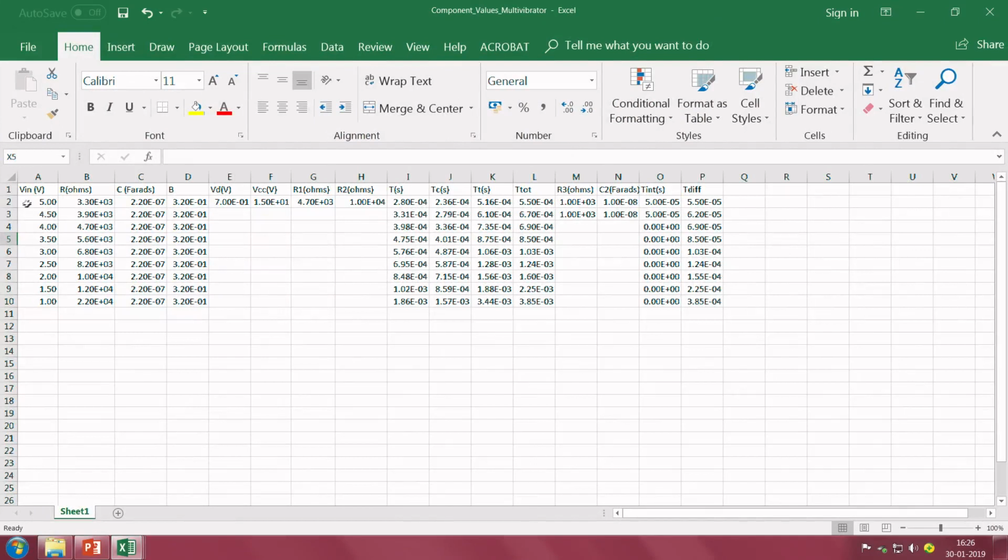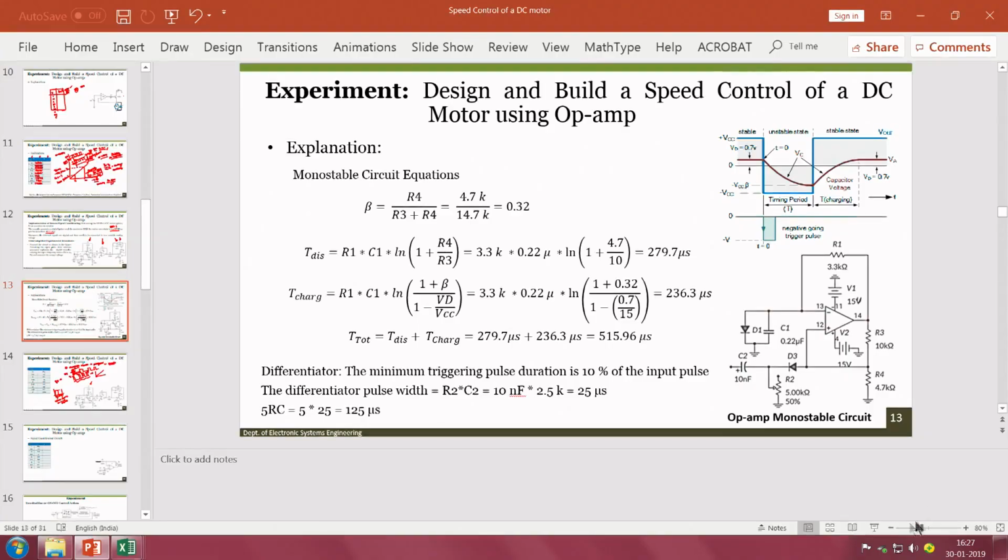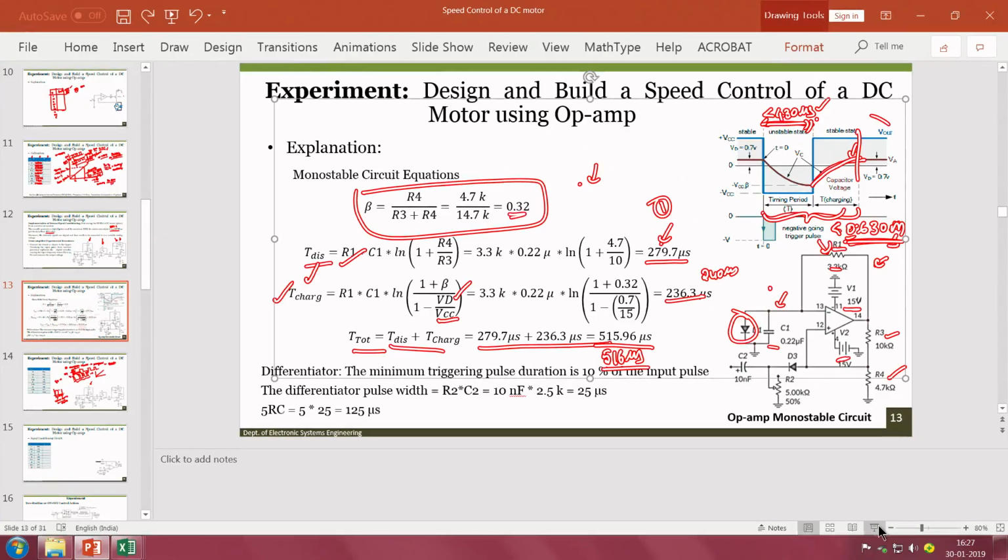We have gone with different capacitors and different resistors, and seen the on time for each, and whether everything, adding these two, is within our limit or not. So, we have done different calculations to match the resistance and capacitance values. Finally, we have come out with R as 3.3 kilo ohm and capacitor as 22 microfarad, which meets our requirement, right.